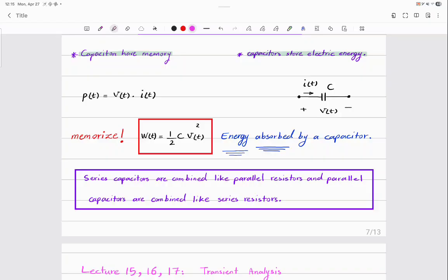And then based on that, remember always, when you replace the inductor with a short circuit, one thing that could happen is a resistor gets shorted out, okay? I'm not saying always, but always keep an eye on that, okay? That's the first step. But in the first step, what do we need to calculate? We did the circuit, we simplified it. What do we need to calculate?